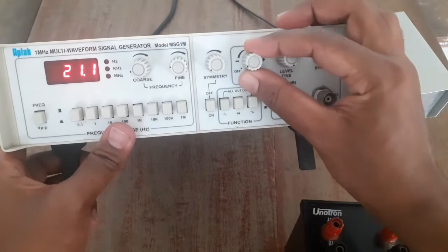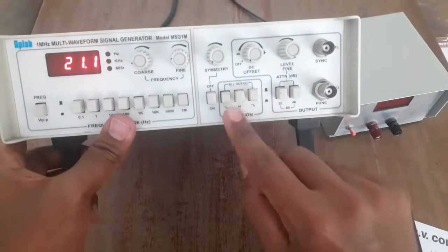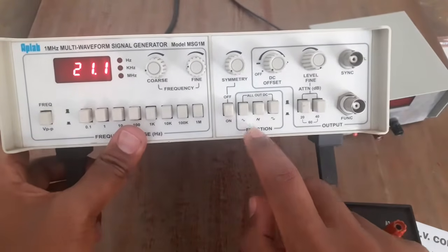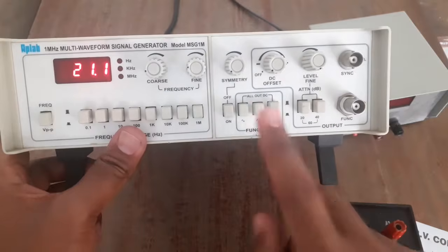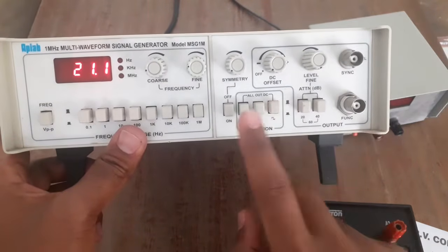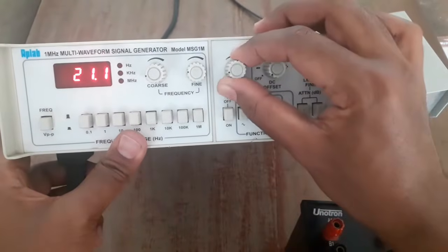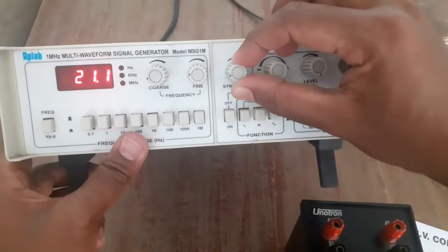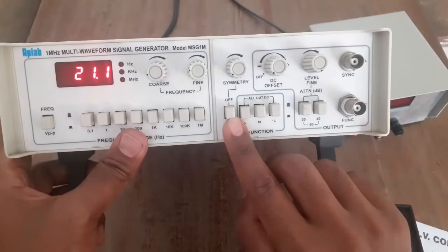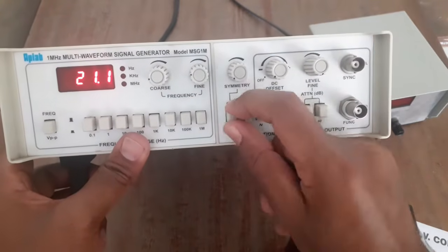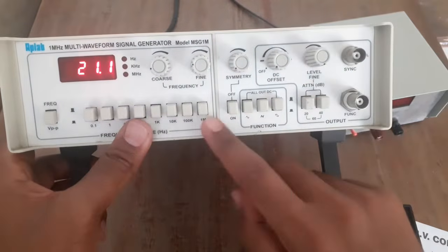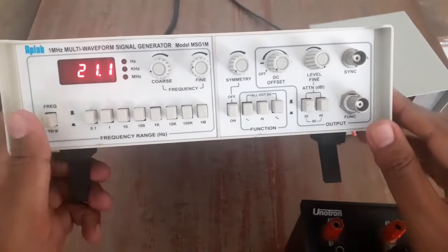This is DC offset, it should be minimum. And here other three buttons are there. This signal generator can produce a sinusoidal wave, triangular wave and a square wave. For our experiment you need sinusoidal wave. So let this be pressed and other two be unpressed. And this is symmetry, you can even tweak the symmetry of the sine waves which you are having. So let that be off. Let it be minimum and let this button be unpressed. So don't press this, let it be outside. And this should be minimum, this should be minimum, and this level should be maximum. Fine. So now let it read frequency.